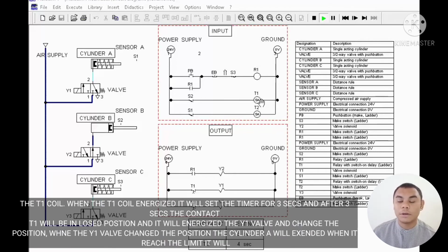When the T1 coil is energized, it will count. It will set the time for 3 seconds, and after the 3 seconds, the T1 contact will be in the closed position and energize the Y1 valve and change the position.